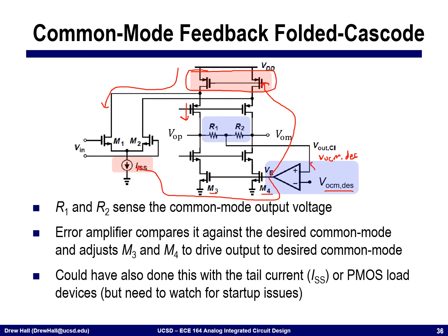Using the common mode feedback to bias these transistors actually simplifies the overall biasing of this amplifier, since then every transistor in the load stage has the same current, and it's very easy to bias this tail current. These two transistors in a folded cascode are the trickier two transistors to bias, just because they contain the sum of these two currents, especially if they're not equal.